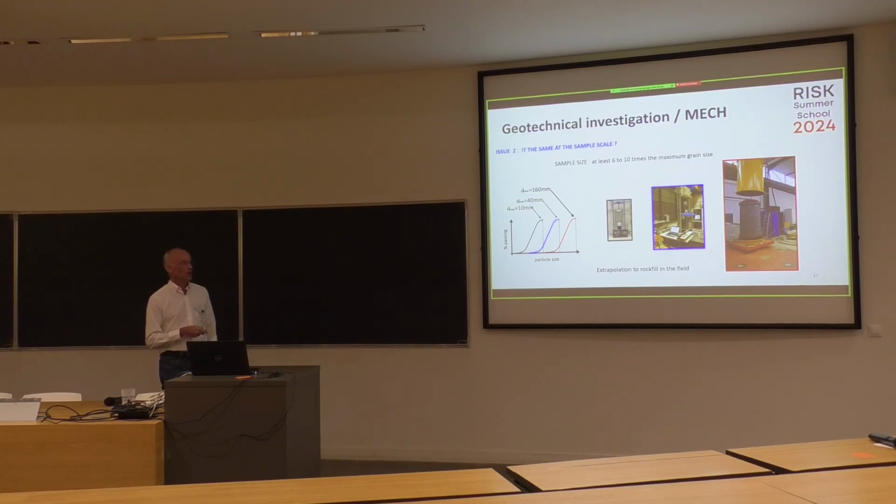millimeters. And then we carried out tests on the largest triaxial cell in Europe with a sample diameter of 1 meter. So here the mass of particles is more than 2 tons, 2,000 kilograms. And a test takes 2 to 3 weeks. Okay?